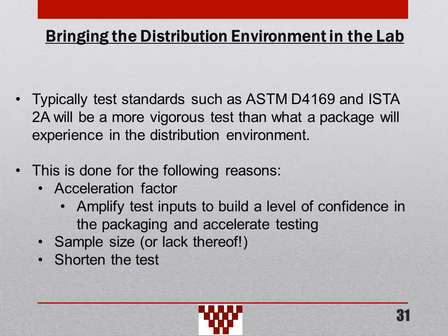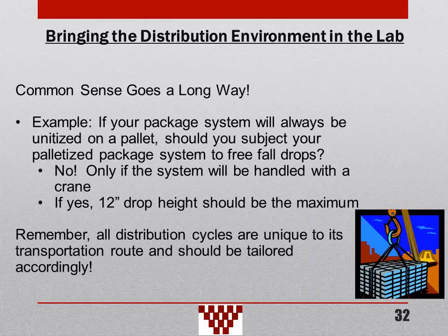But what we like to tell everybody here is common sense goes a long way. When you design your package for your distribution environment, you just think about what your package or your product will be subjected to. Here's an example: if you have a package system that will always be palletized and never leave the pallet, should you subject it to free-fall drops? You think about it, and the only reason it's ever going to be free-fall dropped is if you handle it with a crane.